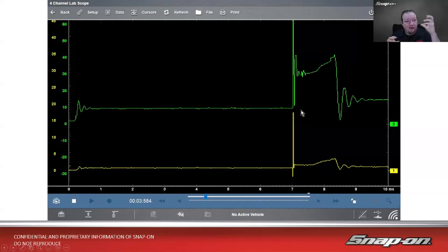So basically that's your difference in voltage from a low voltage to a high voltage. You see this is spiking at, what, 15, 16 volts? This is spiking at like 70 volts. And that's still not in a kilovolt scale, right? Because it's not using that scale for the secondary ignition adapter.